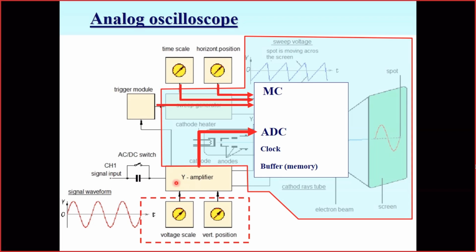With an analog scope, it was a very hard task if the pulses are very short and come very, very rarely, so you may have no time to see the pulse because it appears and disappears immediately. So there were some special so-called memory luminophores, which accumulate data and have a very long afterglow period after the excitation. But it was really a headache to remember, to fix somehow, to record somehow the short pulses.